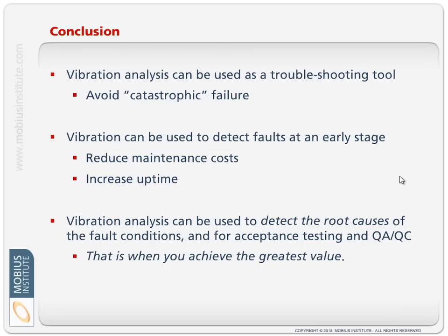All of that is good. All of that justifies the training and the equipment. All of that is important, but you can do so much more, because if we detect those root causes like unbalance, misalignment, lubrication problems and soft foot and so on, if we detect those early and correct them, then the bearings probably won't fail. Depending on your industry, we might improve quality, we may reduce energy consumption and all those things if we eliminate those root causes.